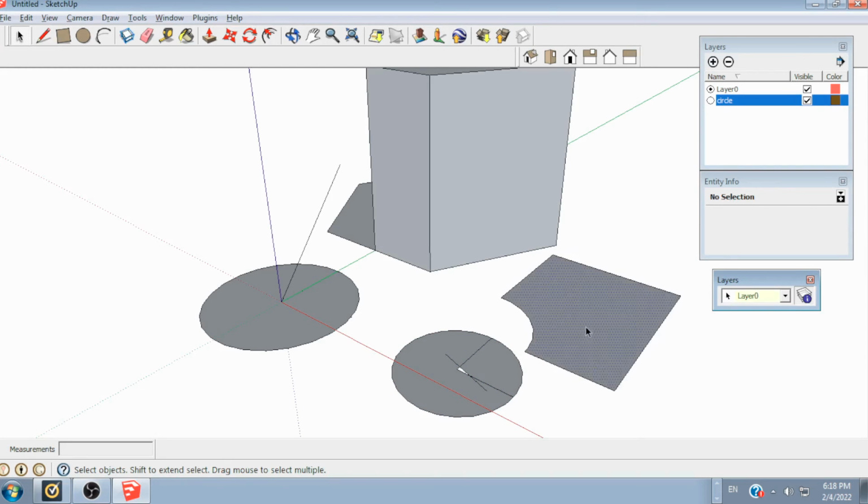So now, click over here, it's layer 0, click over here, it's circle. Now up here, if I uncheck the visibility for circle, everything that's drawn in layer circle disappears, including anything inside of it. All the layer 0s inside of it go away as well. This is really, really handy when you're making a part that has different components to it that you want to render visible or not.